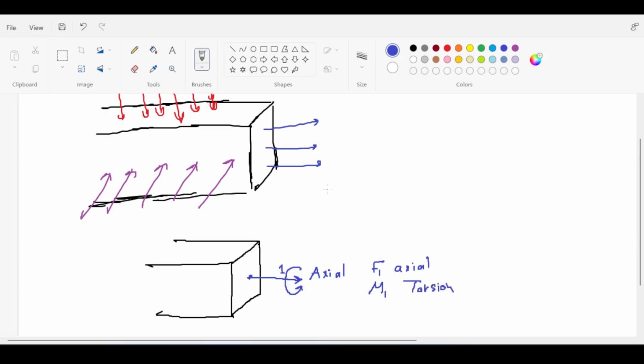That's axis number 1. Axis number 2 in Etabs goes up, local up. This might correspond to the local z-axis if you want to call it z. And this has, of course, 2 things. You could have forces on that axis, and you could have moments on that axis. A force on that axis, I will call it F2 now, is basically your in-plane shear. The internal shear force resulting from, of course, you need to talk about the directions later, the gravity loads, basically, the in-plane loads, which are the red loads here.